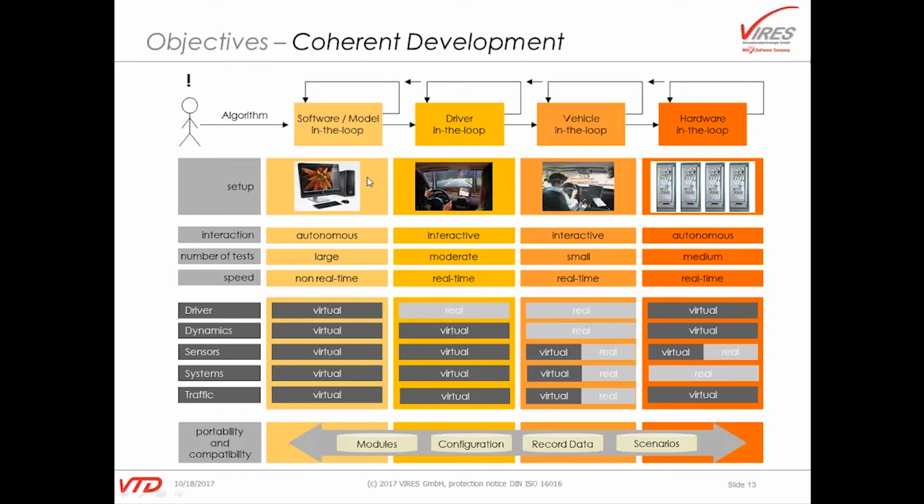A specialization of this is if you bring the driver into the loop, which means you will be exchanging the virtual driver with the real driver with something like a mock-up or steering wheel or just a gamepad, and you will be doing a typical driving simulation that you know from the games. This is where we go to the real-time domain due to the human being involved in this. And this is one of the environments where our software will also run. And we have a couple of installations at our customer sites for this.